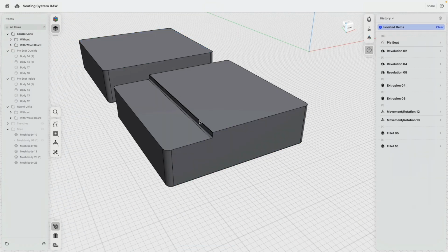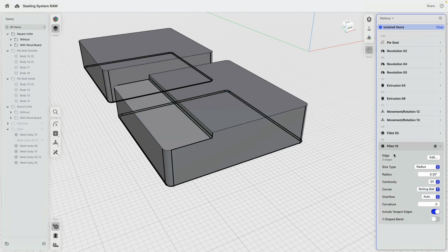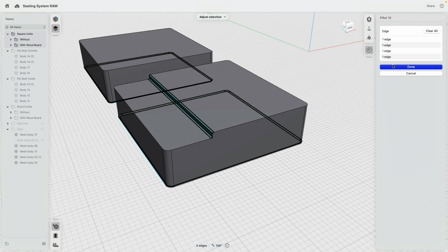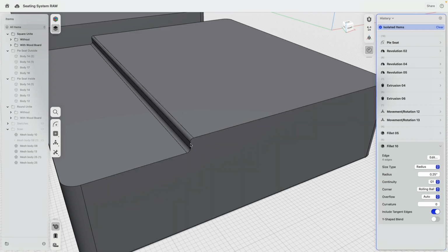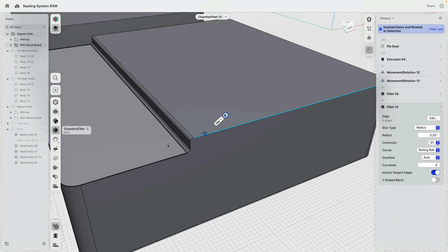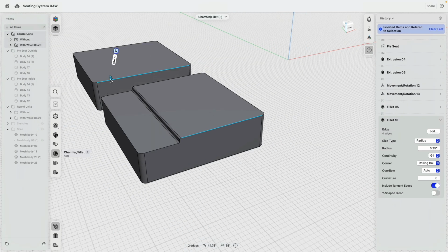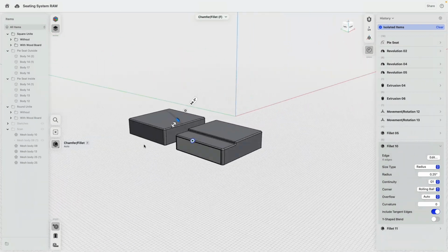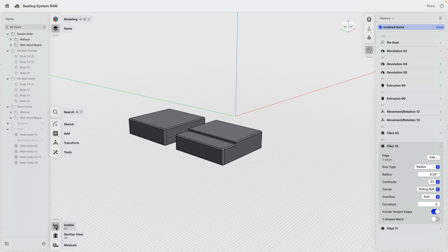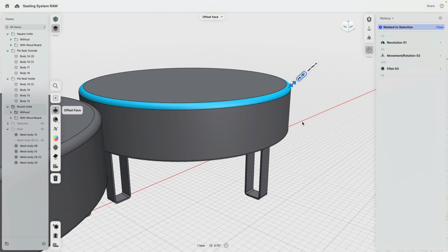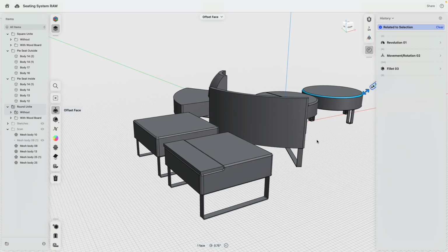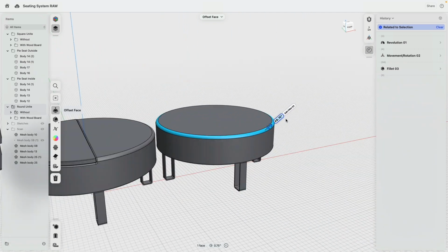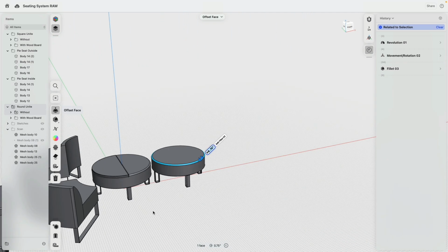Isolate this one more time. Yeah, we have to do the following here. We need to add this to it. You see now I have a line, arc, line, arc, line. So we can select this one and say 0.5 and round this one, because I think the value we have is 0.75. Let's say, I'll keep this. Good.